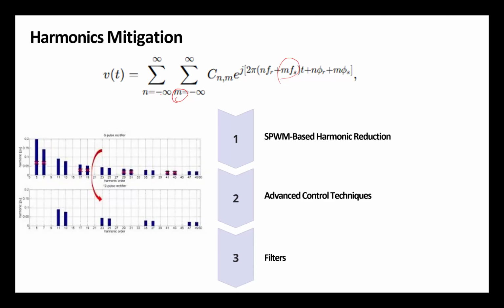How could we add another level of protection, another level of correction? Then the filters kick in. You do your best on switching, but at the end of the circuit, you put a low pass filter for a power system, or band, or whatever kind of filter that you want to design. Normal design is a low pass filter. Okay, you put a low pass filter to damp all the high frequency harmonics and let go of the low